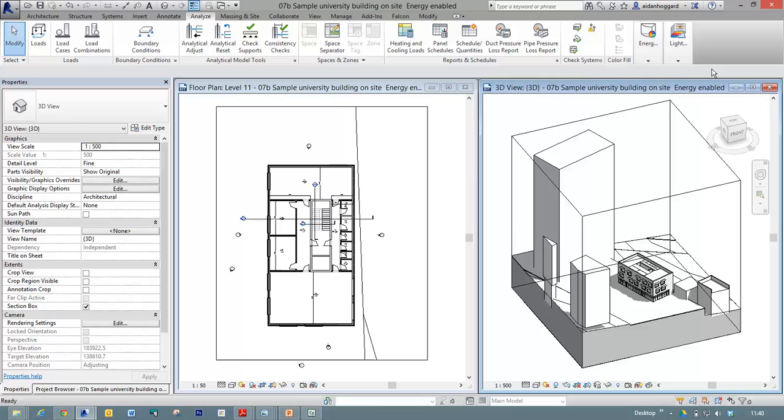Okay. Now, ideally, the easiest way forward is to run the export through Revit as we did before. If the model is too complex, you have to go about it in a slightly different way. And you have to export GBXML from Revit, and you have to import GBXML into Green Building Studio. Now, I'm not going to go through that today because hopefully you never need to use that, but I've got a video that I've produced that shows you how to do that, which I'll put onto Moodle. And I'm afraid it's just one of those limitations of the software at the moment.